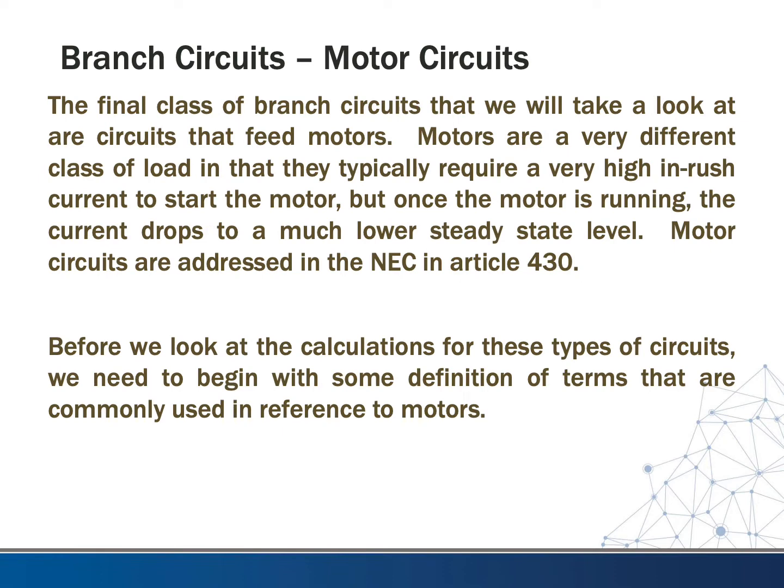So we're going to look at motor circuits. This is the final class of branch circuits that we want to take a look at, and these are circuits that feed motors. Motors are a very different class of load in that they typically require a very high inrush current to start the motor, but once the motor is running in a steady state, the current then drops to a much lower level. Motor circuits are addressed in the National Electrical Code in Article 430.